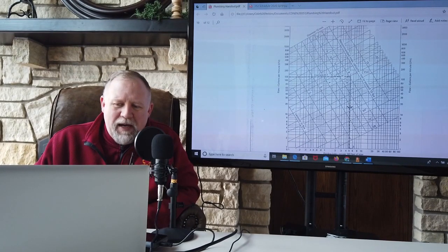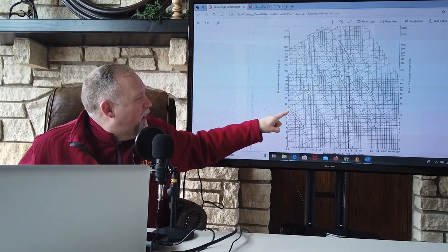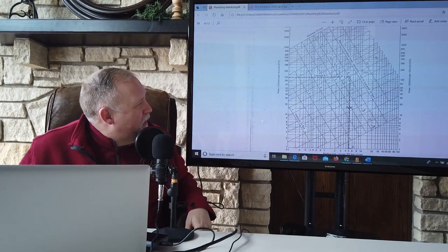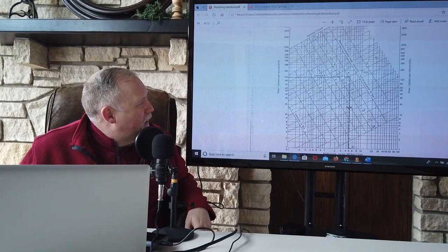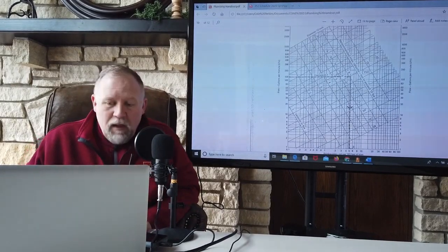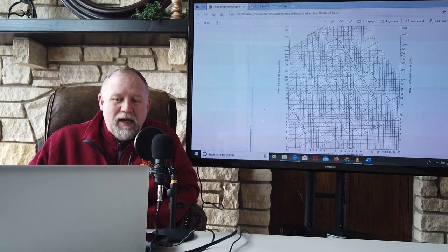So what you do is go back along this curve until you hit one of these diagonal pipe sizes. And what you will find is that a 2.5-inch pipe matches up with the 100 gallons per minute line right there. I'm going to put my arrow cursor on it. I hope you can see that. And that is your actual pipe size you're going to use. Yes, it's slightly oversized, but way cheaper than buying a custom one. So that is the point that we're going to monitor.